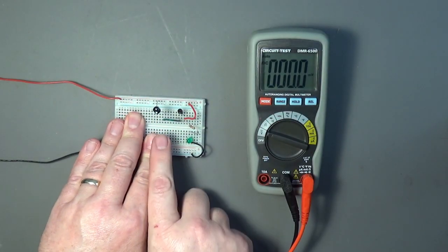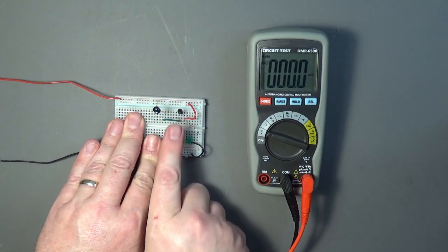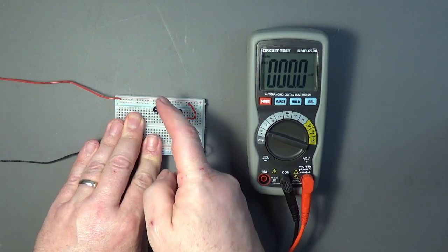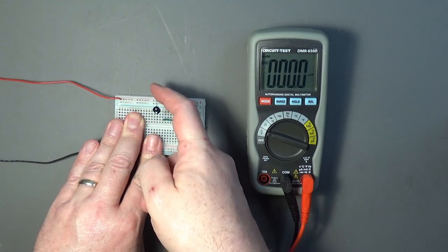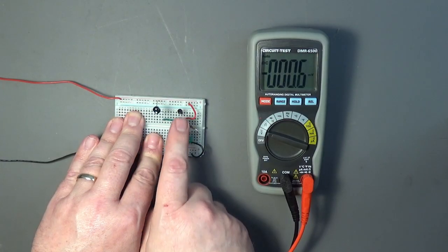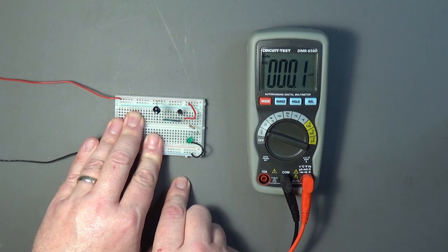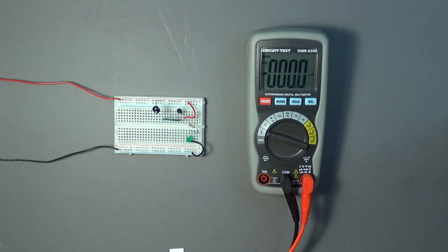And what I've got is the photodiode hooked up to a transistor. The transistor here is amplifying the rather small current from the photodiode, and the photodiode is hooked in backwards, so it's in reverse bias, and that'll allow just enough current when the light's on it to turn on this transistor, which should turn on this little LED here.